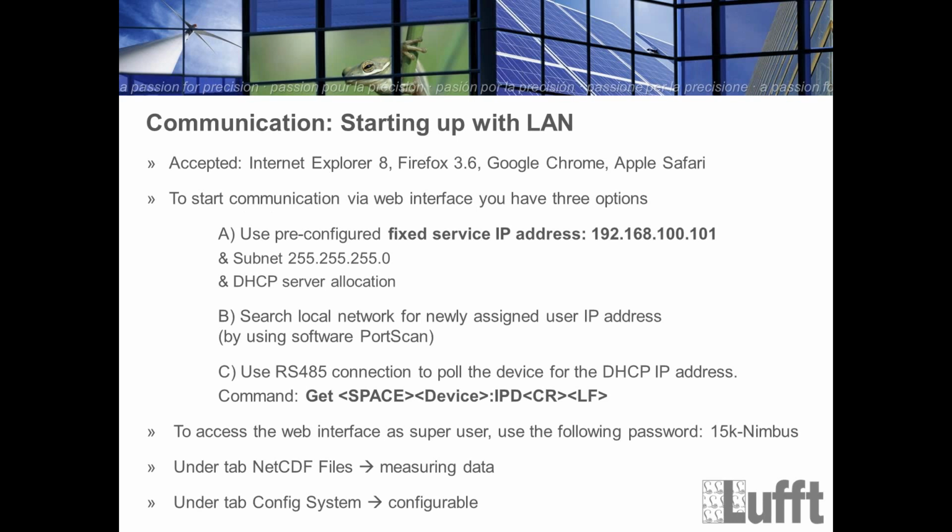Yeah, for the Ethernet LAN connection, for years any of these kinds of browsers can be used to access the instrument via LAN. There's one fixed address which is always available for service purposes. It's this 192.168 address. So you can always use this address to enter the web interface of the instrument with a direct connection, I have to add.